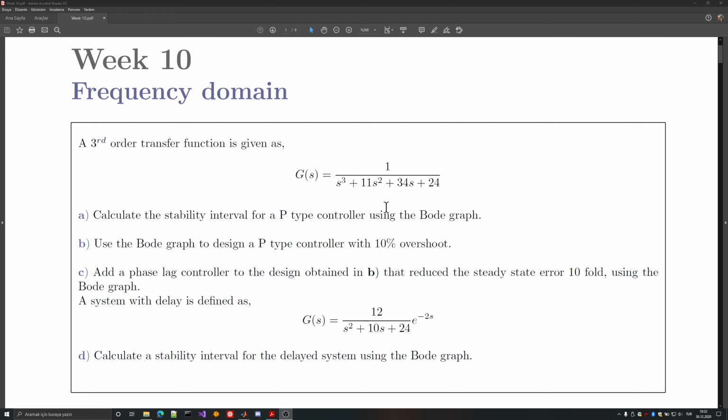Since this is a linear system, the thing that will happen is that sine will be transformed into another sine wave. So the only difference will be in gain and phase. So we are basically observing this gain and phase change versus the frequency. So let's say we increase the frequency, but the gain drops at a certain point, and even though we are increasing the frequency, the system doesn't change in the gain that much. We might assume that this is a low-pass filter or low-pass behaving system. And here the phase is very important, since this will give us hints about the stability of the system.